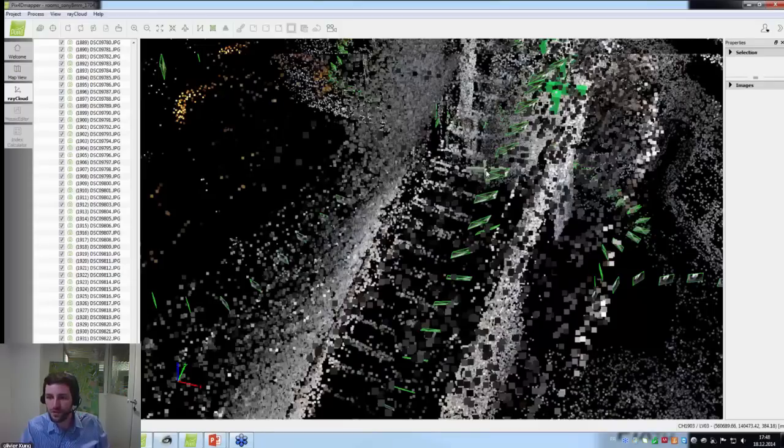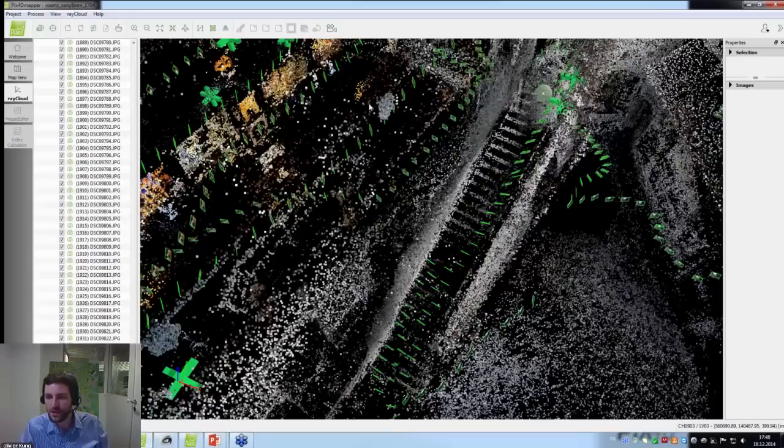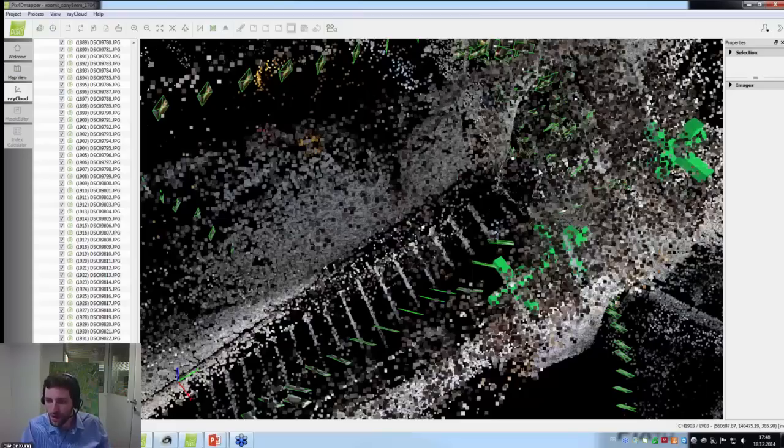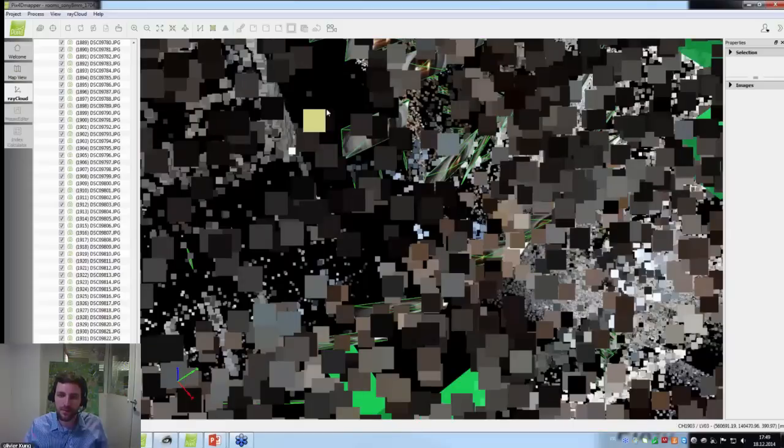At the entrance of doors, as it's much more challenging than normal corridors, there it's really recommended to take a bit more pictures. So not every 50 centimeters, but more like every 20 centimeters, like it's done right there when we are entering a new room, because all the environment changes a lot, even with a fisheye camera.